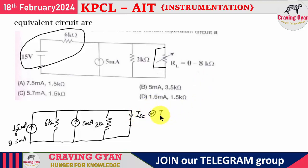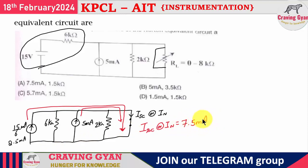it is also referred to as Norton current. Now please think over it in this way. This current will be flowing in this path only. It will not be flowing through the resistor. Why? Least path. Even this 5 milliampere is also flowing in this short circuit path only. Then what is the value of this short circuit current or Norton current? The value will be 5 milli plus 2.5, that is 7.5 milliampere. Option A is going to follow.